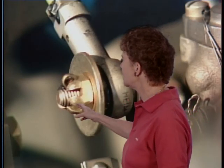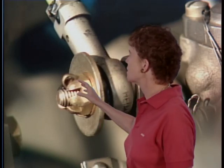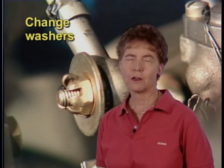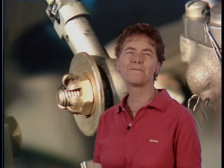Now, let's assume that you're using an aircraft bolt and a castellated tension nut in order to attach a particular component to the aircraft structure. What happens if the cotter pin hole is not aligned within the recommended torque range? What should you do about it? Well, the acceptable practice is to change washers and try it again. And that's what you need to know about the nuts and bolts of aircraft hardware.